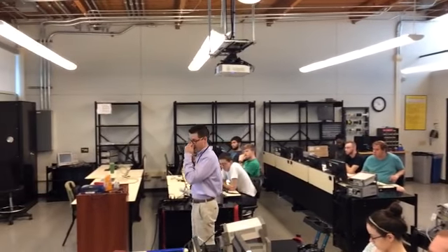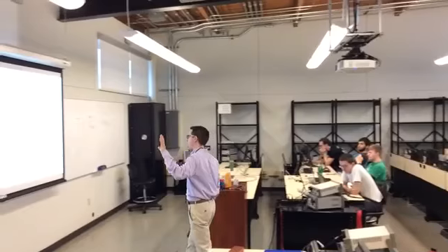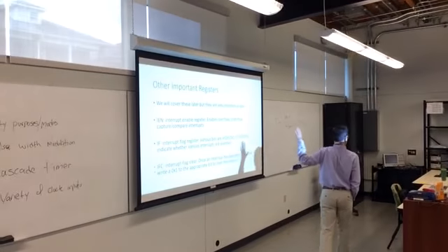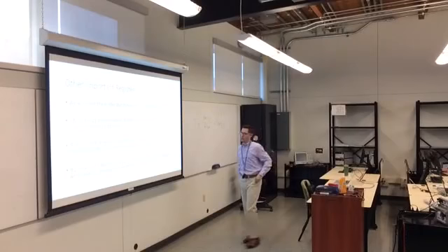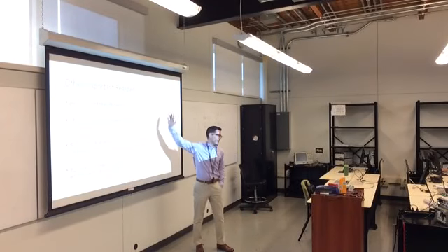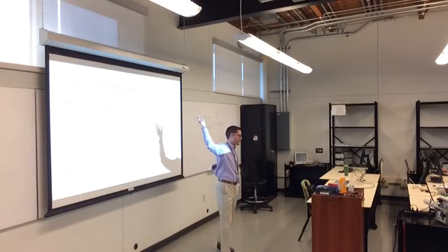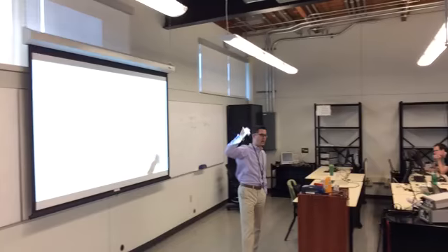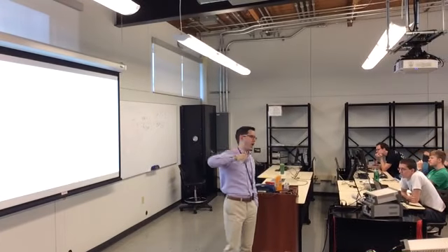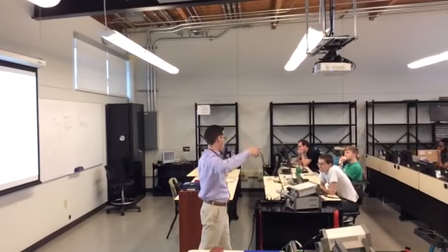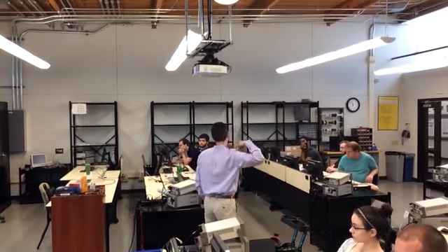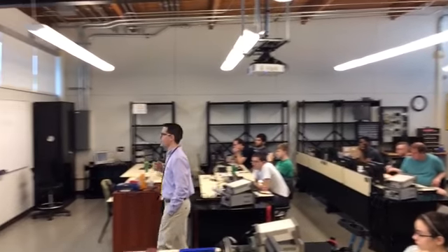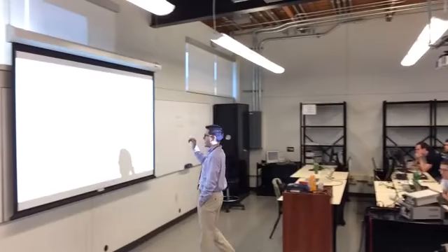So some common conventions that you're going to see when dealing with all of these peripherals is that every peripheral has some sort of interrupt-enable register. If an interrupt is not enabled, it does not occur. It does not occur in the sense that it does not get serviced. Nothing happens.